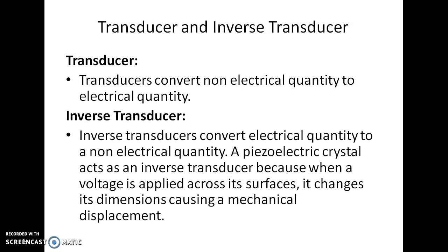A piezoelectric crystal acts as an inverse transducer because when a voltage is applied across the surface, it changes its dimension, causing a mechanical displacement. Means the voltage or the electrical input will be converted into mechanical output.